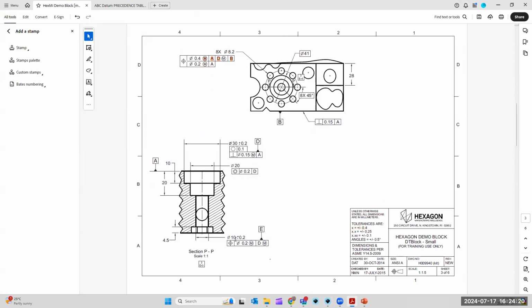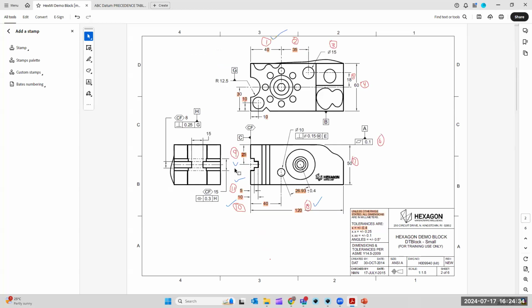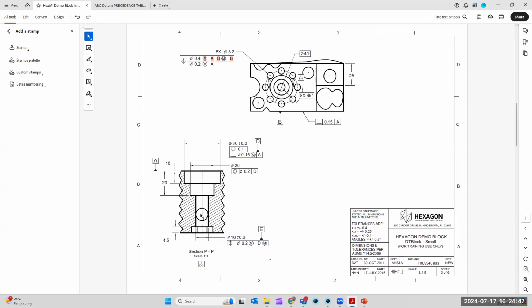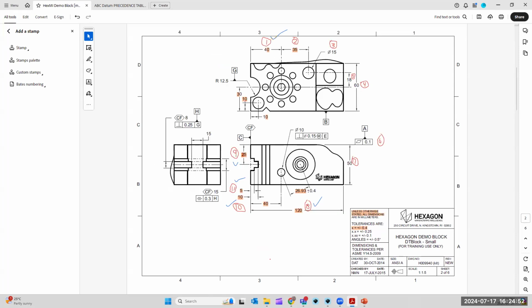Right here, right there. So you could actually get more creative here. That hole that we're measuring to has also a diameter tolerance and a true positional tolerance. We could measure this at the same time as this by building it as a cylinder, but I don't want to get that complicated yet. We're just going to go with the circle for now. I'll show you why you might use circles sometimes, but understanding that that feature is the same feature as this feature is sort of important to recognize. So studying your drawing is a good start on how to program correctly.